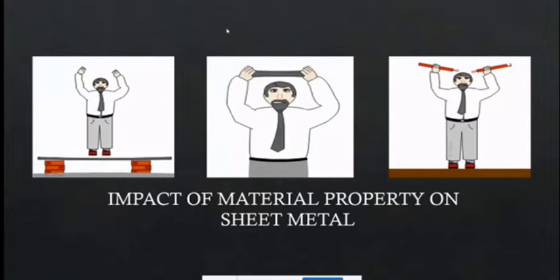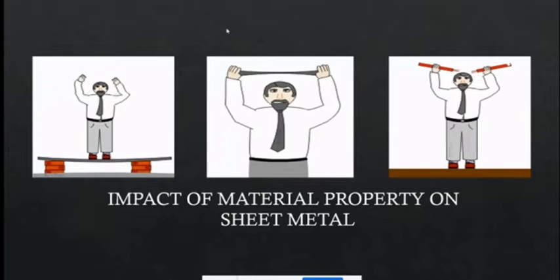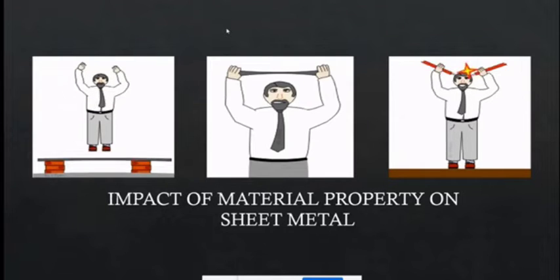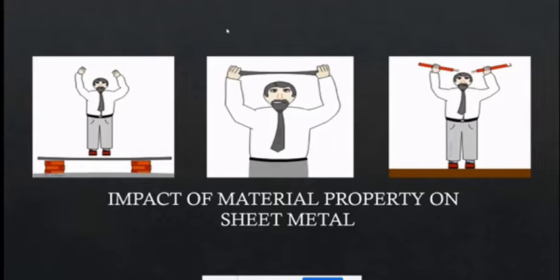Thank you, Swapnali. My topic is how material property impacts sheet metal forming, precision, and tolerance. Variation in metal thickness is one of the most common challenges when achieving bending tolerance. Sheet metal can have variation in thickness throughout a single sheet or between sheets. The nature of the rolling process often means sheets are thicker in the middle than at the edge.